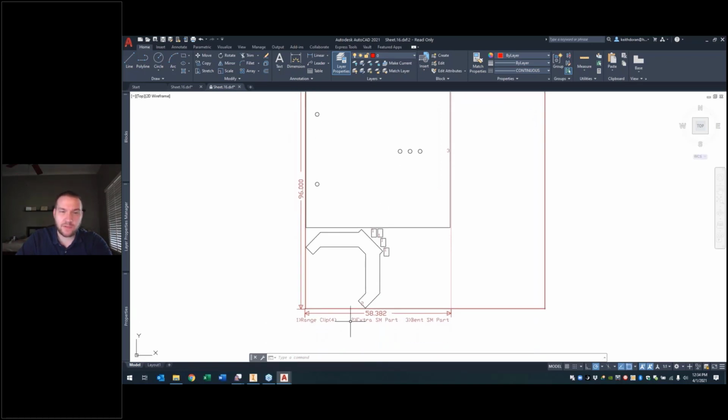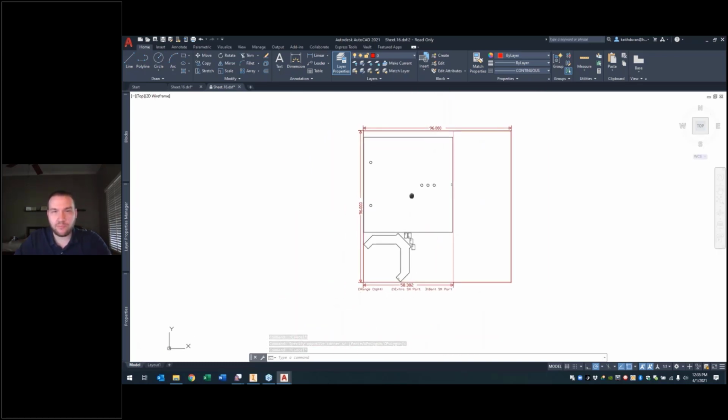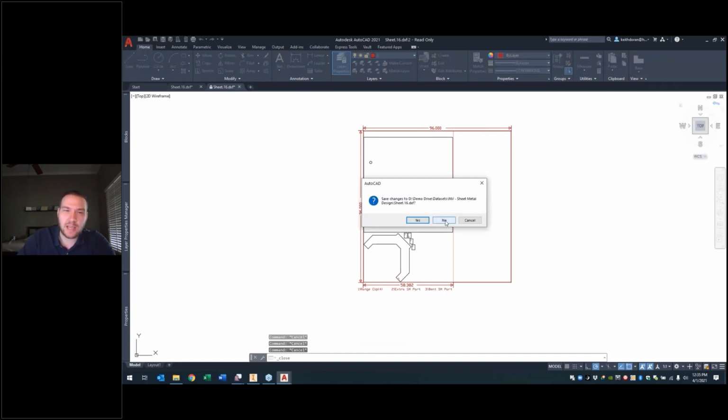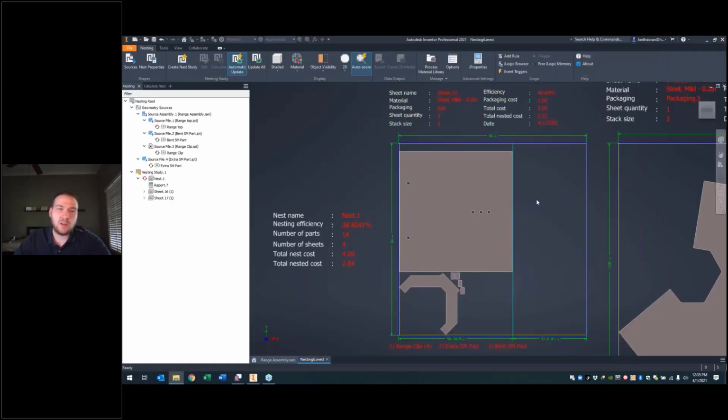From here, it does mark each file. This data does get layered on its own. So you can see in here the dimensions are on layer 1, the objects are on layer 0 within this space. So everything is all laid out as necessary to potentially grab this information and push it into a simple CNC routing system. The alternative would be to take this data and in turn work with it within Inventor and use the Inventor CAM tools to work with these objects.